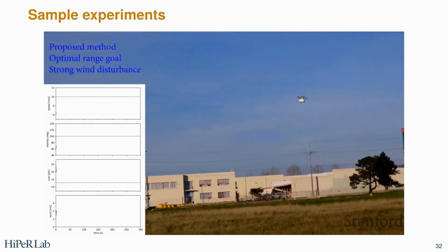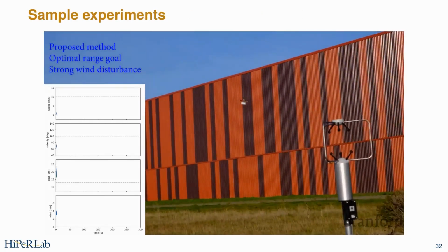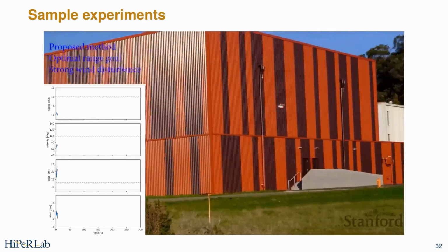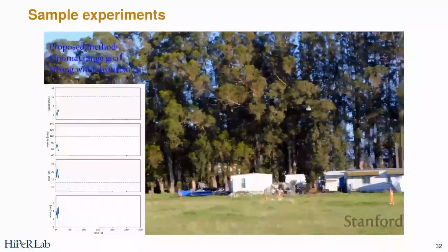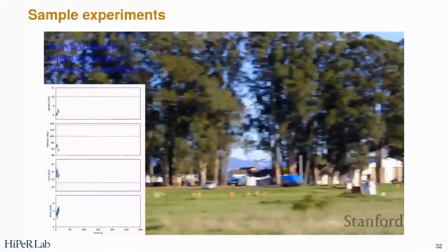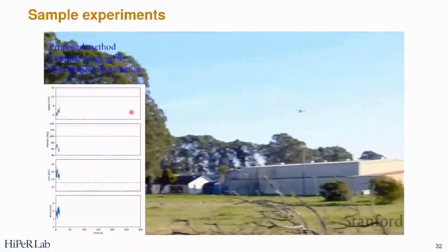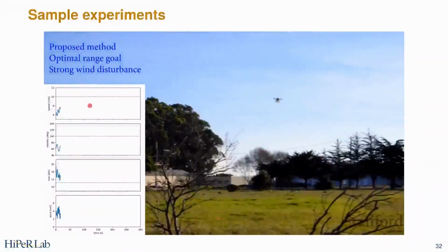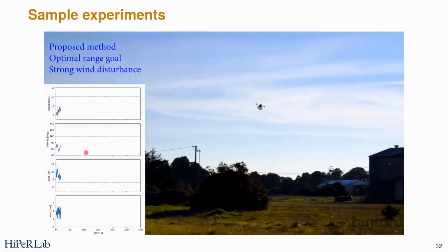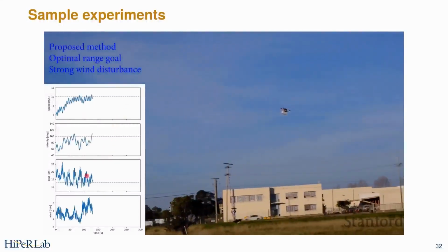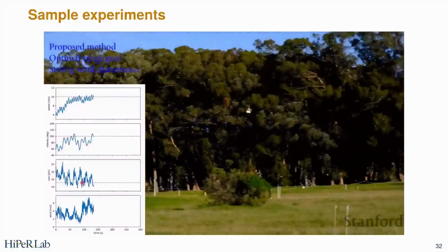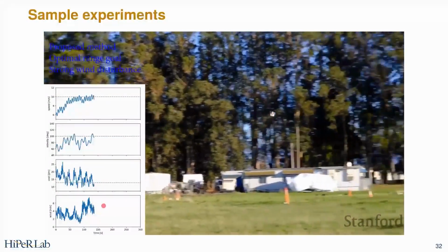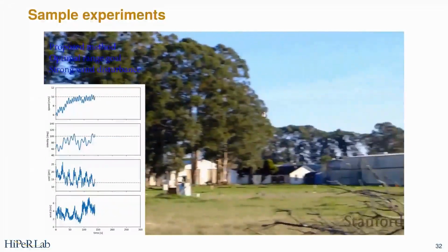But what this gets you is a system where we have a drone flying in our outdoor space. This is flying a large circle in lieu of a straight line, so we don't need to worry about line of sight. But this drone is flying this large circle. We have a graph here that's the forward speed at the top, then the side slip angle, so the 2 degrees of freedom that we get to vary. There is the energetic cost per unit distance, so joules per meter. And then the bottom is just the local wind as we measure it from a base station on the ground.